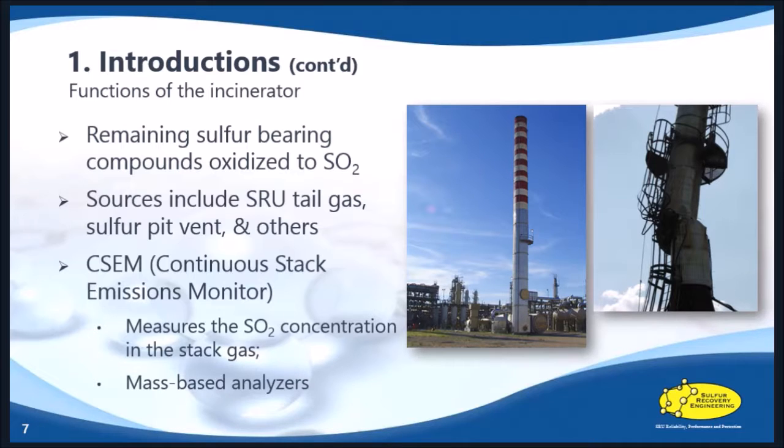Air is supplied to the incinerator and stack by two different means. Either it's a forced draft or natural draft, and in several cases it would be a combination of both. Forced draft air supply provides more precise control for the burn ratio and excess air control.